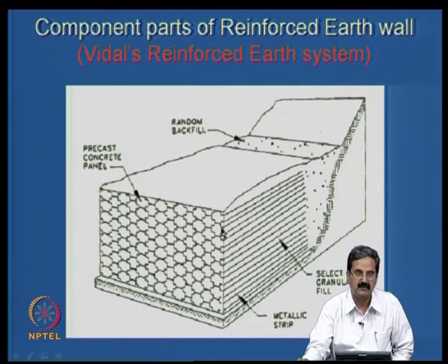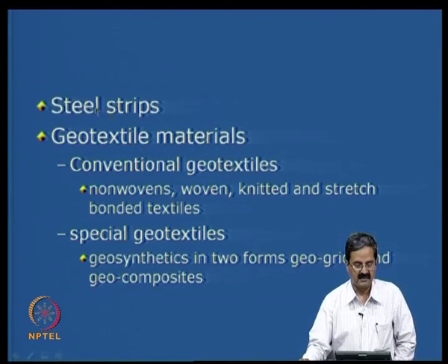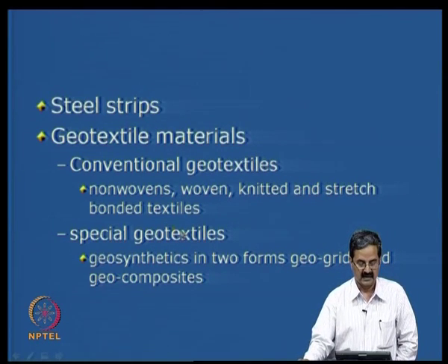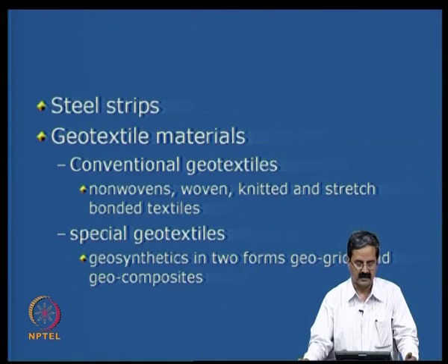In fact, the same company has continued and constructed a lot of reinforced earth walls abroad and in India, and it has been a very useful technique. You can have steel strips as a reinforcement, or geotextile materials. The conventional geotextiles can be non-wovens, wovens, knitted, stretch bonded, many types of materials that we saw earlier can be used as a reinforcement material.